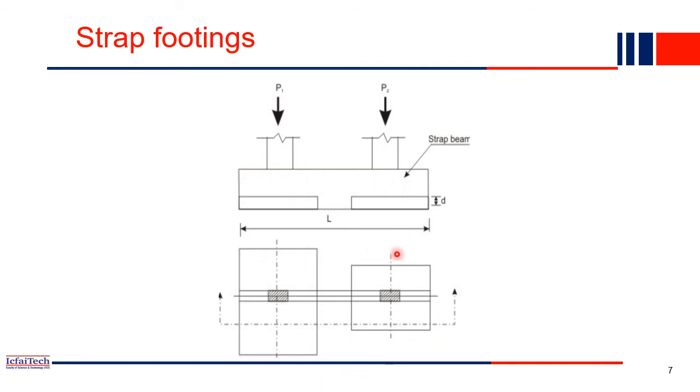Like if you see, this is the same diagram in a plan view. You can see this is one footing, this is another footing. Because of some constraint, maybe on this side the boundary wall is here. Although you may need a much longer footing area, because of the boundary wall you cannot extend this footing. So that's why the footing size here will be reduced. Whereas here, this is the middle of the structure, so you have the larger area for the footing, right? But here, because of some reason, we cannot increase the foundation size.